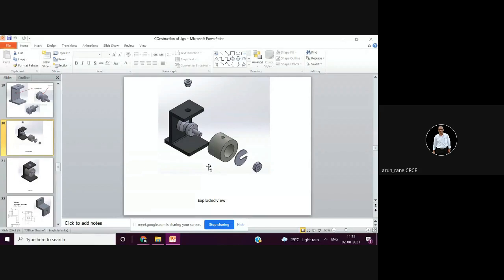We think that we will support the entire 100 mm, but no, even at two ends it will give better location. This actually reduces the manufacturing cost, because suppose this hole is finished 100 H7, 100 plus 0.02, and you are making a locating post of 100, then you have to make the entire 100 mm length within tolerance. But if you are making only this 10 and this 10 within tolerance, then the middle portion you can relieve.